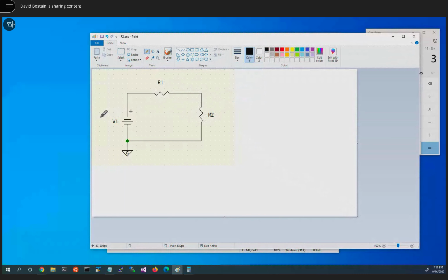So if we were to give this a volt, I'm going to give it an abstract volt, just called V. We know that this particular point is at voltage plus V relative to ground. We also know that ground is 0 relative to ground. So this side of this resistor would be at 0 volts. So 0 volts at V volts. And then this would be something that's in between, which is proportional to these two resistors here. Turns out this can be computed.